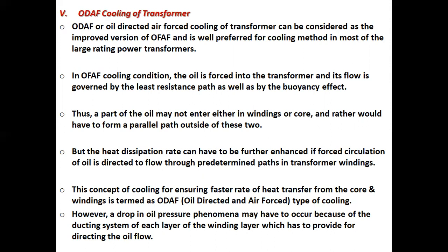But the heat dissipation rate can be further enhanced if forced circulation of oil is directed to flow through predetermined paths in transformer windings. This concept of cooling for ensuring faster rate of heat transfer from the core and windings is termed as ODAF, oil directed and air forced type cooling.